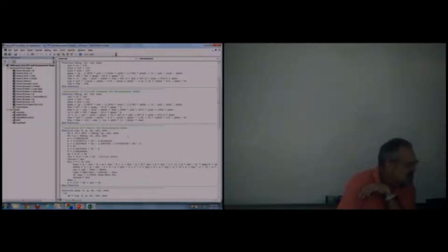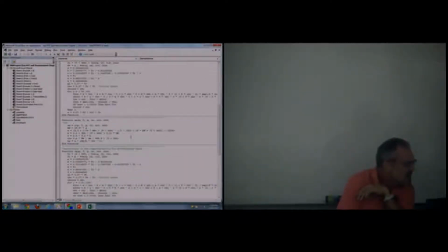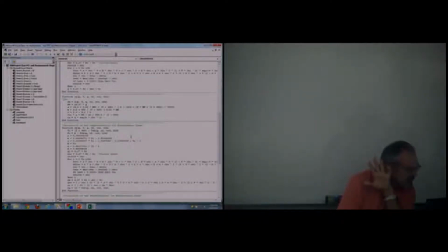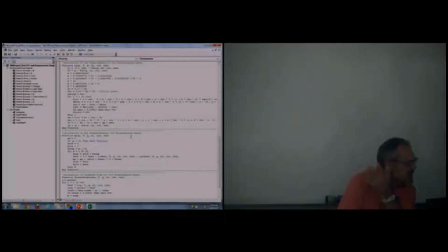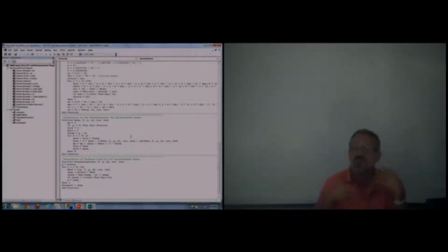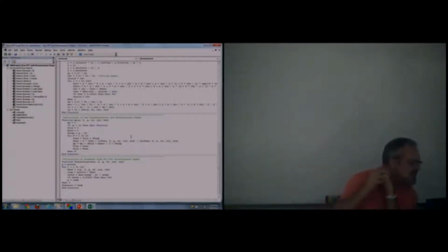And so it uses Newton-Raphson iteration to calculate Z using the Benedict-Webb-Rubin. Viscosity, straightforward. Gas compressibility uses your Z function. Pseudo pressure, what you've got right here is numerical integration. You've got almost all your examples of for loops, do loops, while loops.